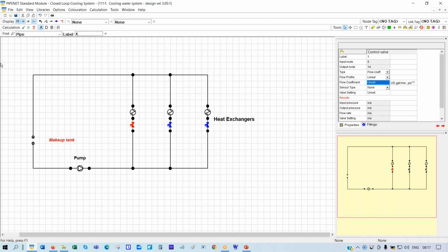And of course, I'm going to choose a valve that's bigger than that, because if I choose exactly that value, the valve is going to be fully open when the flow is what is required. We don't want that. We need a valve here which is only partially open when the flow rate is what is required. So I will input a CV that's slightly bigger than that. We need 131, so I'm going to input 150.